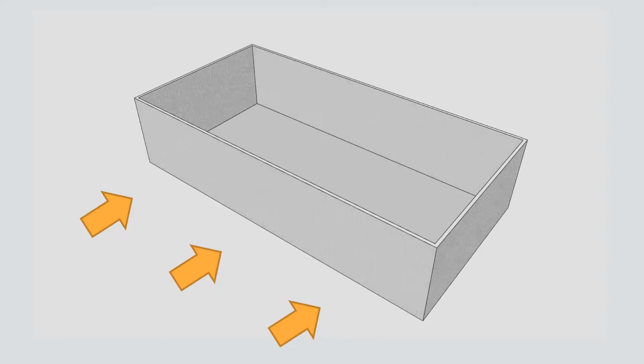One way to visualize the importance of the diaphragm to the masonry can be seen in the load distribution from the walls to the roof and then the roof to the shear walls. Here we see a building with no roof diaphragm. The lateral loads, either wind or seismic, cause the walls to cantilever off the foundation because there's no top support. The wall deflects inward, becomes unstable, and will likely collapse. This could happen if the actual roof diaphragm does not function properly. So, for a safe, strong building, we need a proper roof diaphragm.